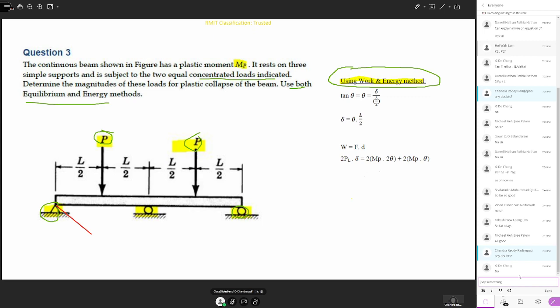So it goes to this, and again from here. I'm just drawing the deflection curve. Of course the drawing is highly exaggerated in the amount of deflection. So it will be like this. This is how the beam will get deflected at the 2 loads when the load is increased to the plastic load.